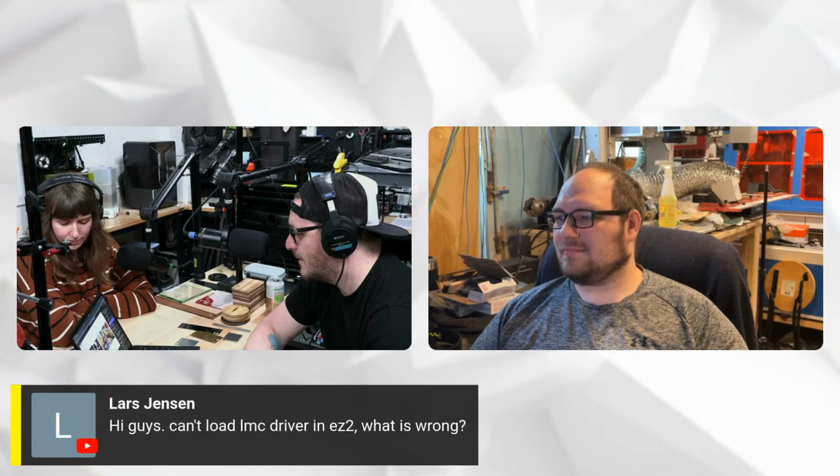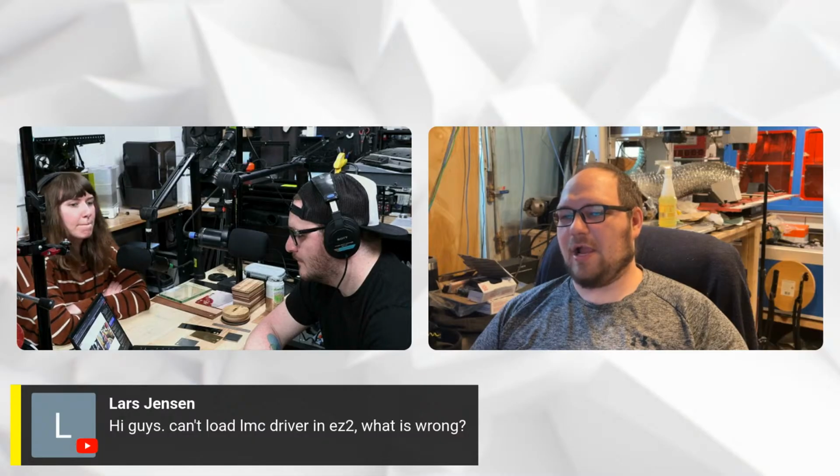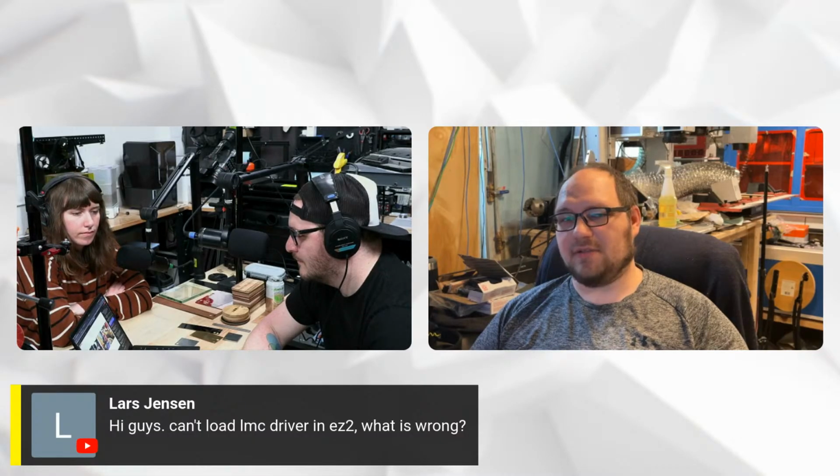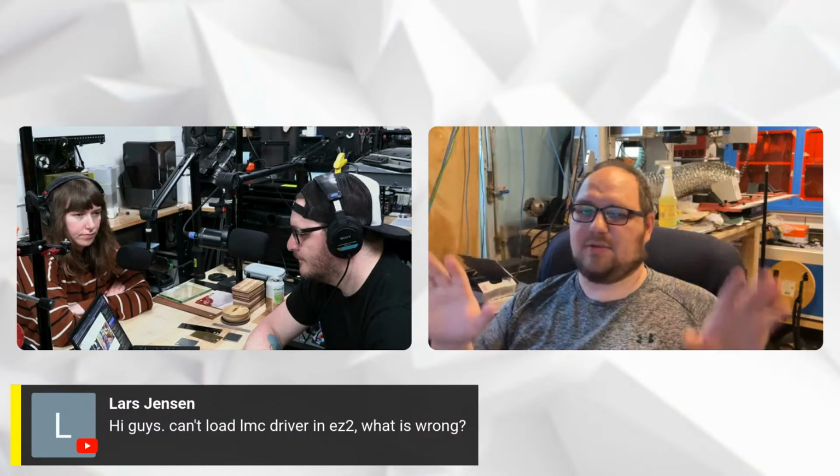Hey, Resin's here. Hi, Resin. Hey, Lars. The reason you're getting an LMC driver error in EasyCAD 2 is because your driver's not installed. If you installed Lightburn and you tried it, that's why. You can only run one software at a time, and each of them has their own drivers.